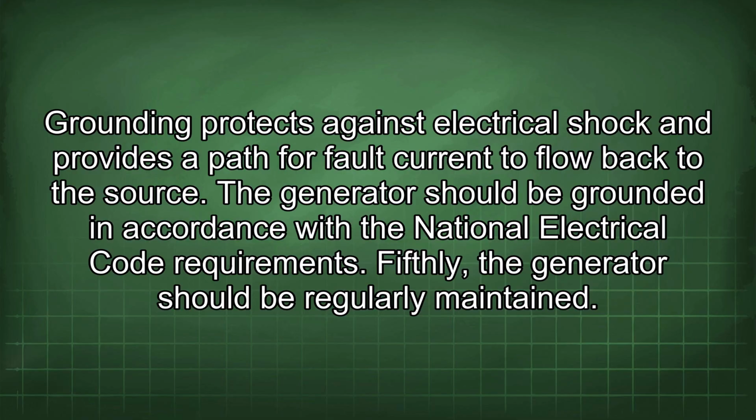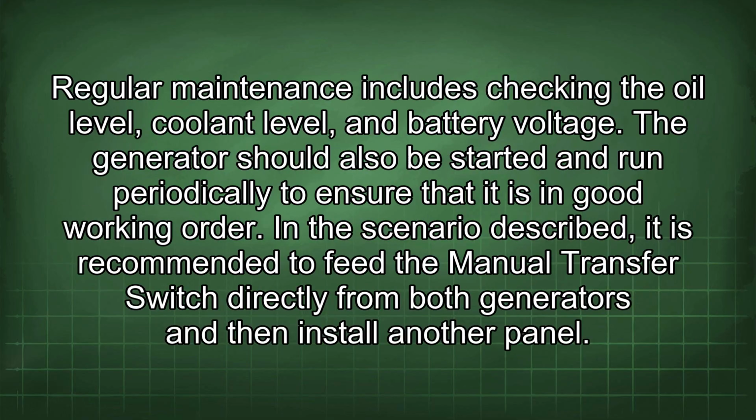Fifthly, the generator should be regularly maintained. Regular maintenance includes checking the oil level, coolant level, and battery voltage. The generator should also be started and run periodically to ensure that it is in good working order.